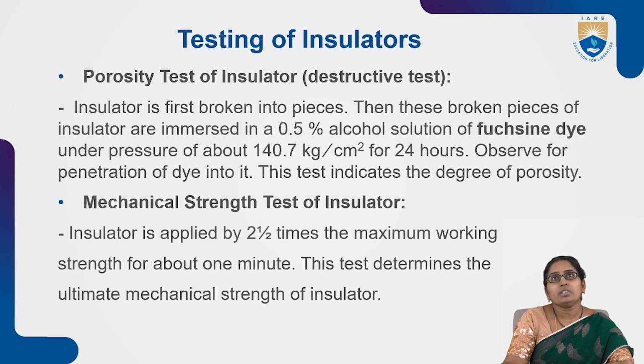What is the pressure here? They mentioned 140.7 kg per centimeter square for 24 hours, and after that they observe for penetration of dye into it. They check for any penetration of the alcoholic solution into the insulator. This test indicates the degree of porosity.